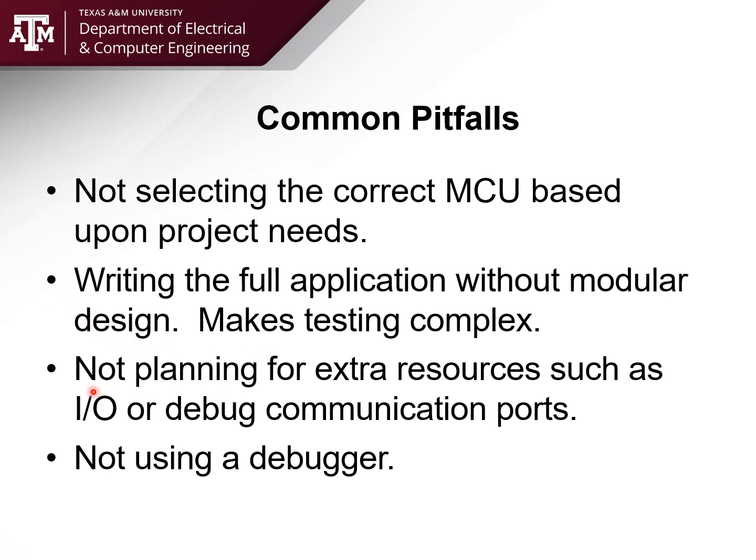Not planning for extra resources like extra I/O or a debug communication port or something like that. You really need to be thinking ahead on that. You have to be thinking about how am I going to test what I'm building. Testing, as a part of being an engineer, is just part of life. I'm going to build and design something, but on the flip side, how do I verify what I design meets the requirements? There's something called the systems engineering V model.